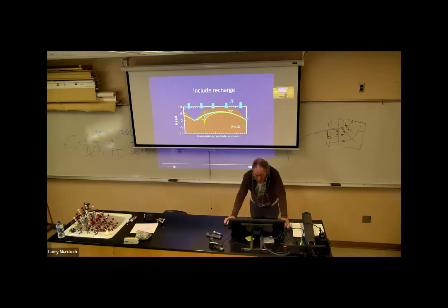So the well has started to influence the stream, but it's not actually removing water from the stream. What it's doing is capturing recharge that would otherwise go to the stream. So the stream will have less water in it, but it's not because the well removed the water, it's because it captured water that would have otherwise gone to the stream.